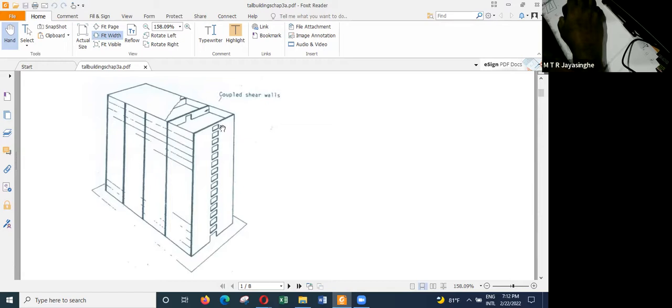The reason is, in a normal building, you can use a shear wall thickness of 200, the minimum that you can cast, unless you have very special arrangements, like flowing concrete and special steel shutters, then you can even cast 160. But under normal situations, with some great difficulty you can cast something like 180, but it's pretty easy to cast 225. So we like 225 type walls. And if it is 250, you have no restriction. It's very straightforward casting.